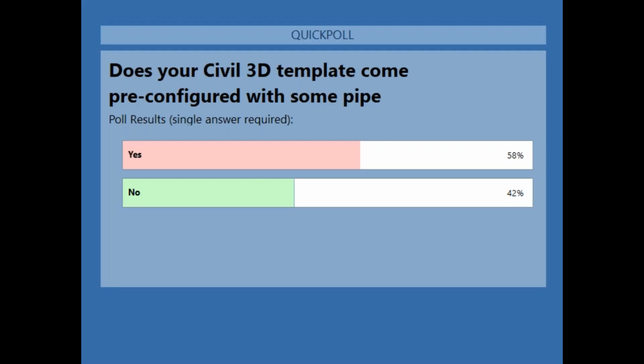The pay item will add existing pipes and proposed pipes onto one line item, right? And Colin and I both kind of answered, yeah, because it goes by part, even if you have different styles applied to a particular part, it won't separate it in the pay item list. I also added maybe afterwards use quick select and manually add it to a different item, possibly as a workaround, but I'll put it to you for further comment.